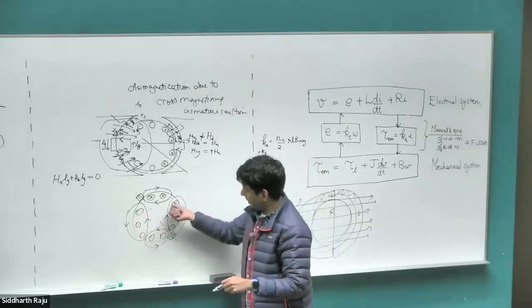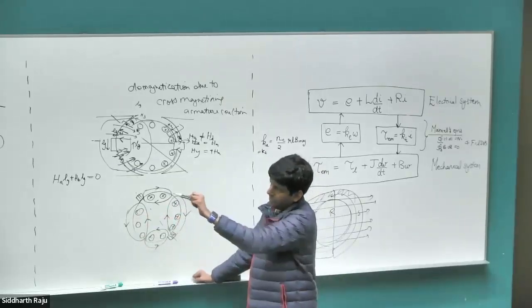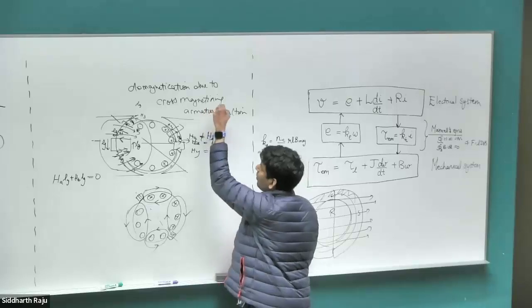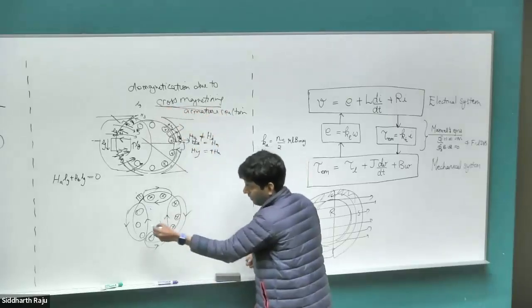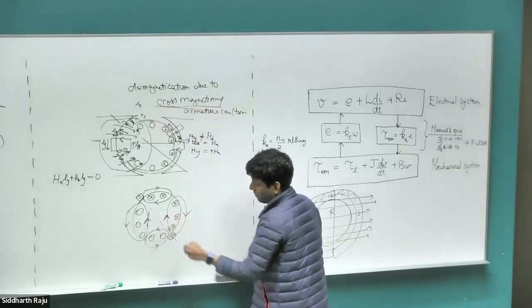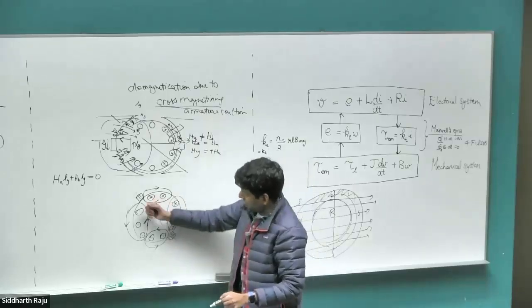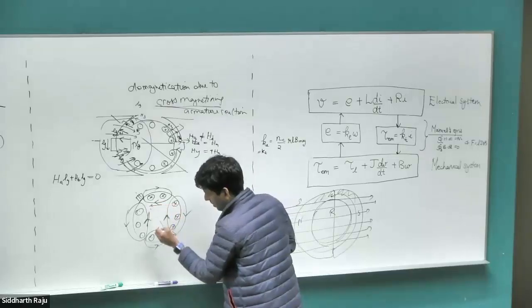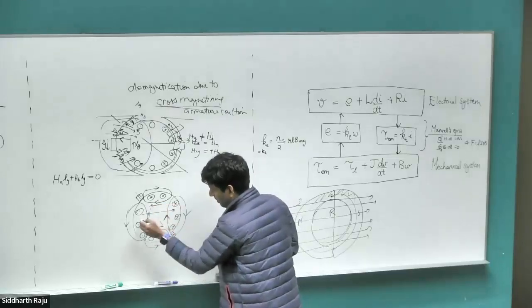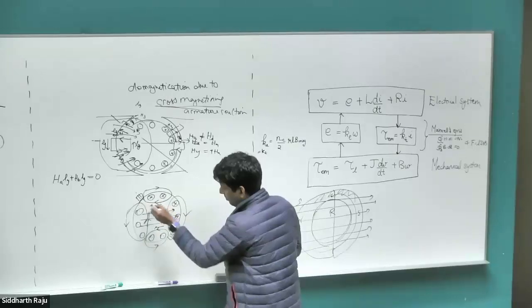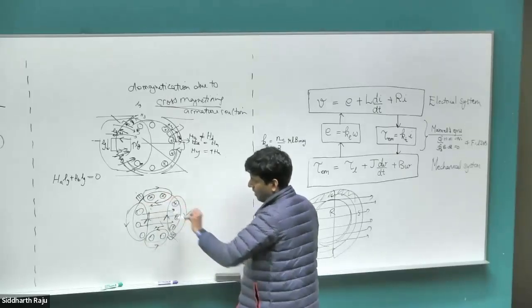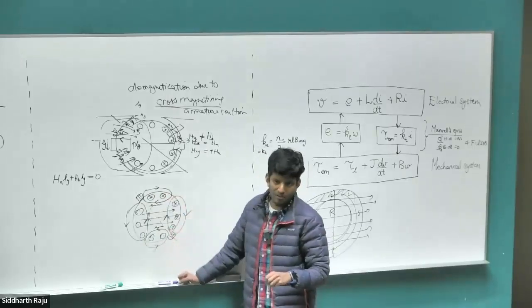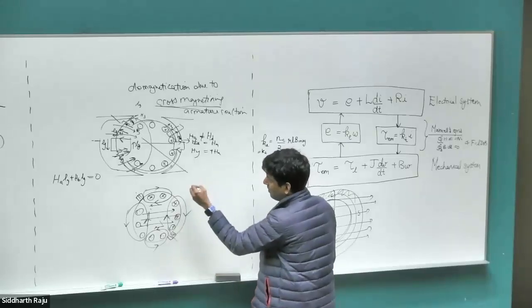So these three sets of conductors and these three sets of conductors are still the same as the previous case, which are just creating cross-magnetization component within the core, right? So within the core, they're only creating cross-magnetic component. But due to the shifted brushes, we now have components which are in the direct axis as well, right? So our external magnetic field is coming like this, but due to our shifted brushes, a portion of the conductors are creating magnetic field in the opposite direction to the external magnet, and this in turn demagnetizes the magnet directly.